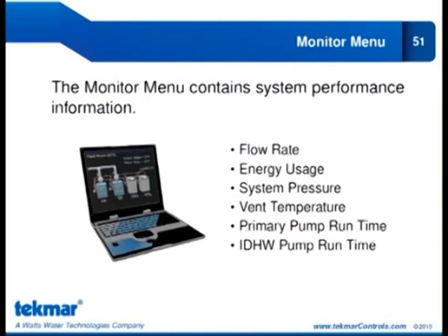We're looking to basically supply a vent sensor, which should capture the lower temperature requirements relative to, say, a non-condensing boiler plant where the temperature can be in excess of 900 degrees Fahrenheit. So if we look at vent temperature, we're talking about common vent temperature. So we're looking to probably supply a vent sensor which is rated for up to 500 degrees Fahrenheit. Okay, so you could definitely use that on any plant which is homogeneous with condensing boilers.